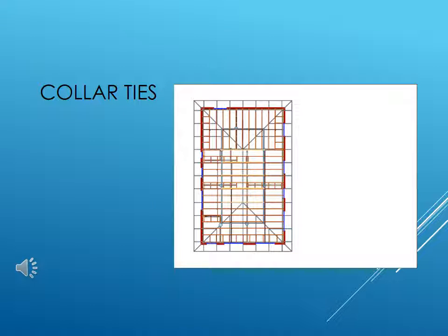Collar ties. Collar ties perform a valuable task in a roof. Their function is basically centred around coupling, and so they couple the roof at the halfway point. Generally, collar ties are placed above an under purlin and securely fixed by two 70mm nails into the rafter, and generally the chippies will put a fixing into the under purlin as well.